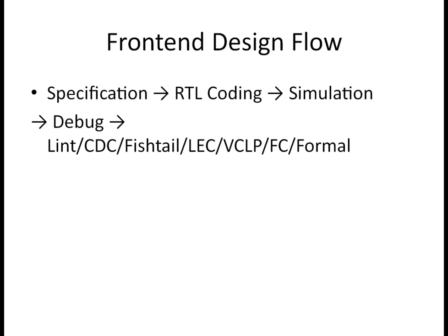The next violation, as I already said, is that in a sequential statement we should not use combinational. We should always write blocking statements in a combinational block and non-blocking statements in a sequential block. If you are not following those coding guidelines, the tool will throw an issue.